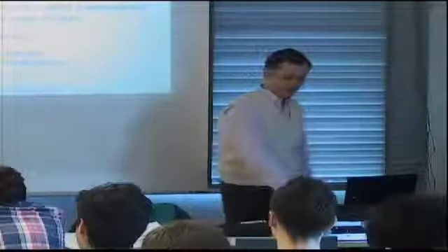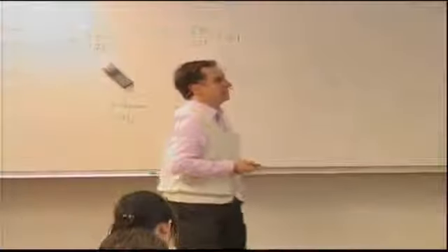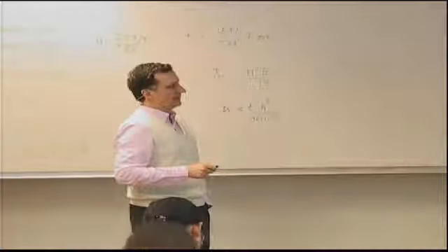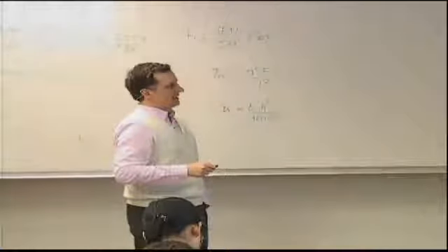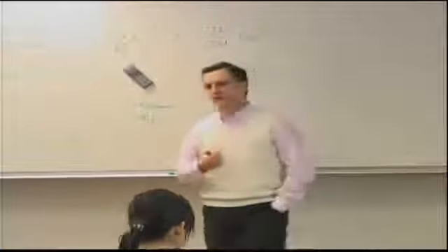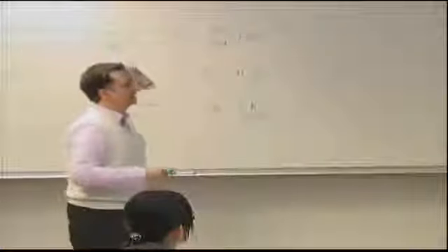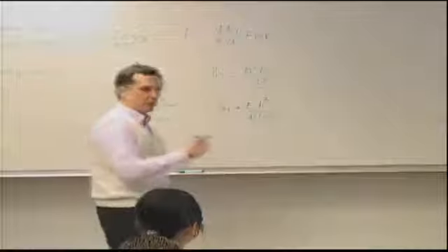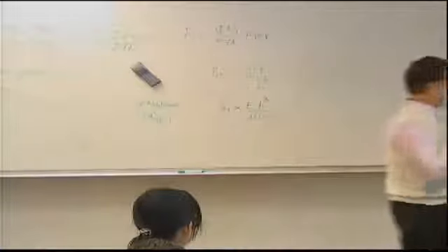So to find this point where I switch from one failure to the other, I would equate the crippling stress with the interrivet buckling stress. Let's say I took the case of one edge free crippling, I would then back solve for the spacing S max. I would get this crazy equation that's telling us that if the spacing is bigger than this value, we will have interrivet buckling. If the spacing is less than that value, we have one edge free crippling. Obviously, if you have a flange that's no edge free, then you wouldn't be using this equation, but that's left to the interested student to derive the expression.